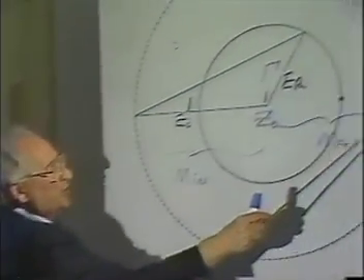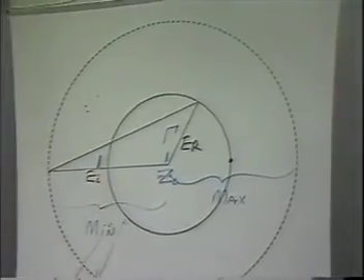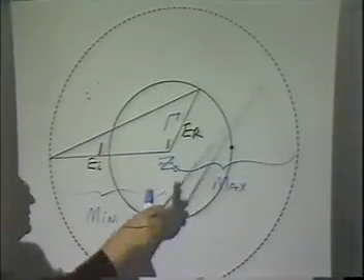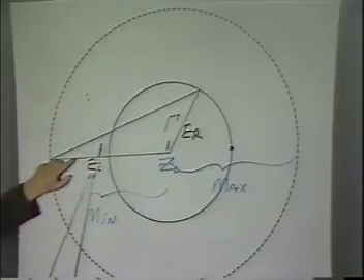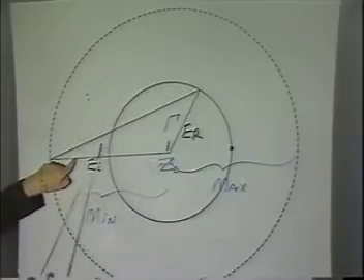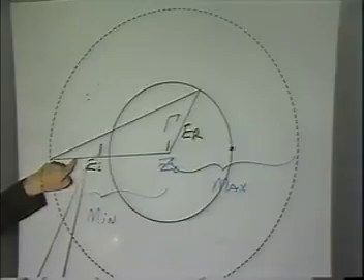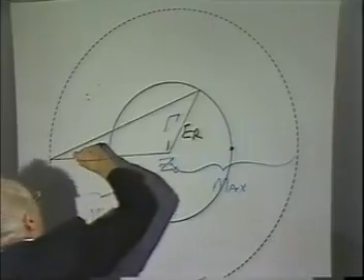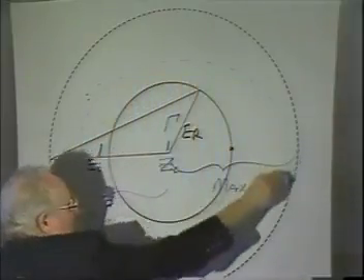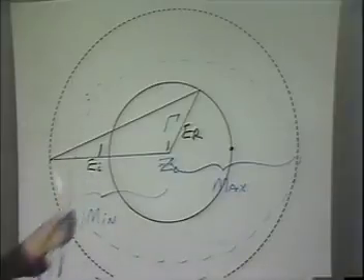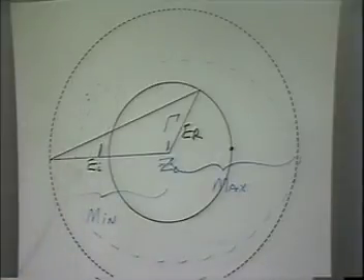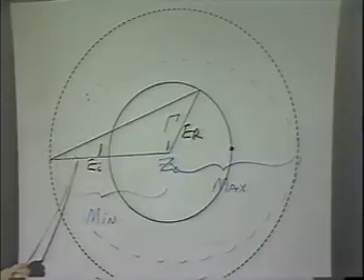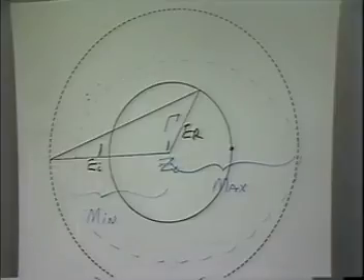Anytime you're inside this circle, we know what this circle out here is. That's 0 resistance. Any circle that goes out here and crosses this axis over here between here and Z0, it's going to be some value of resistance, pure resistance, less than Z0. But any place on the circle, of course, like this, any place on that circle we'll say is 12 ohms. But it's only 12 ohms pure resistance right there. Okay? I don't think you have any problem with that.